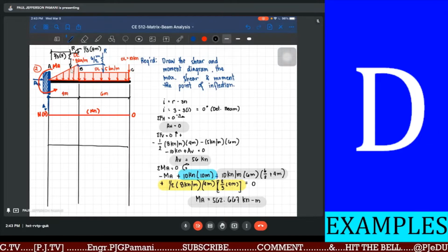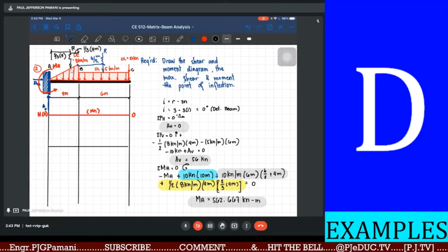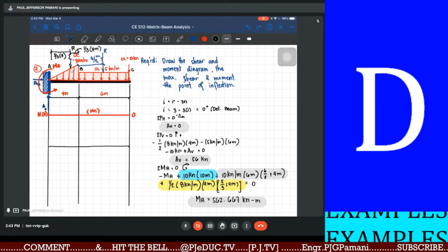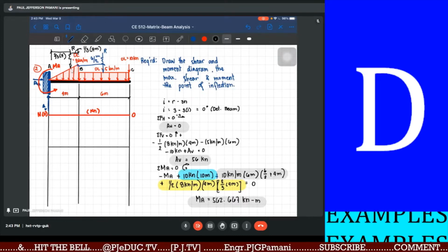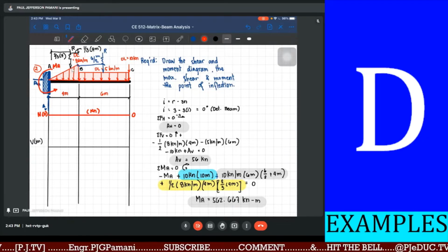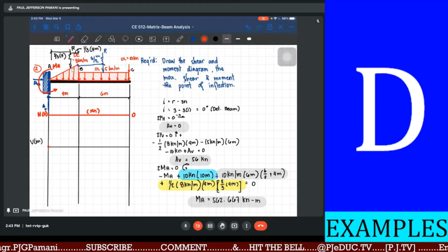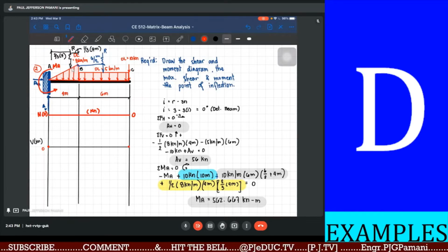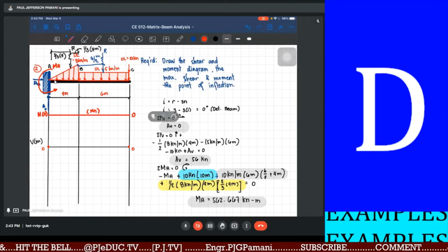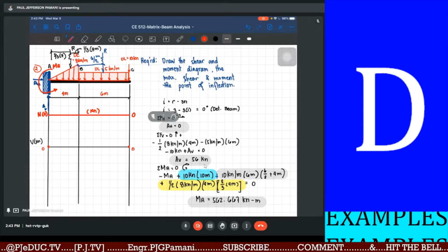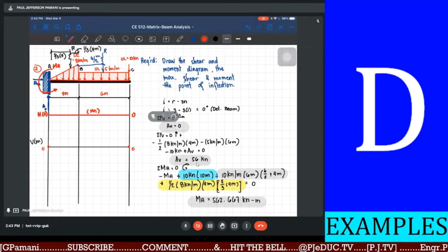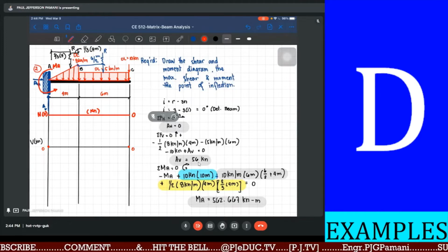So how about the shear diagram? We can now draw the shear diagram. So for our shear diagram, unit is in kilonewton, starting always at 0. Remember, we can always start at 0 and must always end at a 0. Okay, at point A, we have a fixed support, and we have recently identified that at the fixed support, there is an equivalent reaction upward of 56 kilonewton AV.